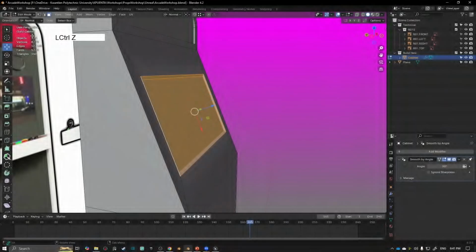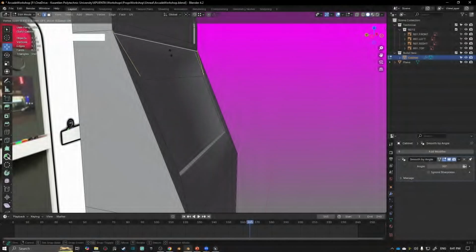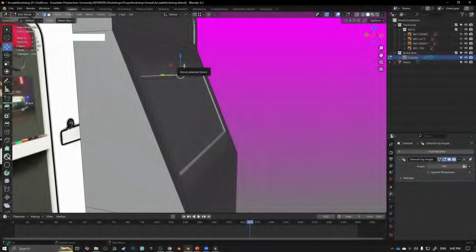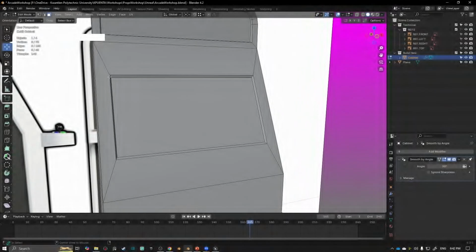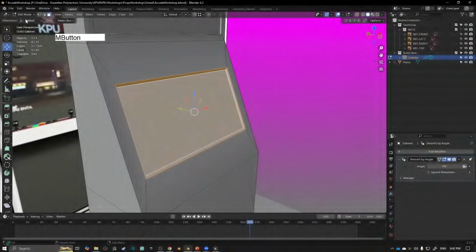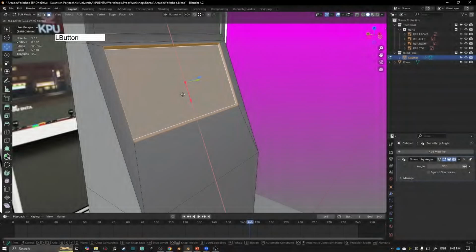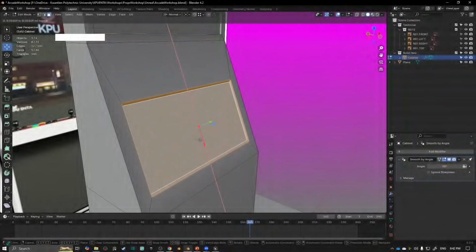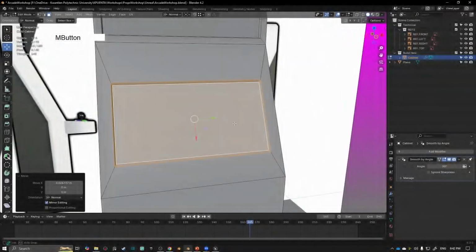If you want to quickly do something like this, let's say you just have one particular edge. If you hit Shift V, that locks the edge to moving along existing edges, so it won't modify the overall surface. But for something like this, if you were trying to move this whole thing, I would say you change your orientation to normal, and then it will just move in that axis, and so it'll slide across that surface.